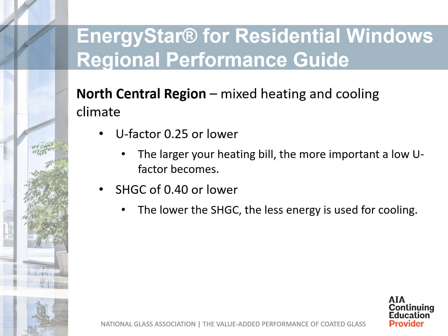The north-central region includes both heating and cooling loads, so is neither dominated by U-factor or solar heat gain requirements. In general, a U-value of 0.25 or less and a solar heat gain of 0.40 or less are required.